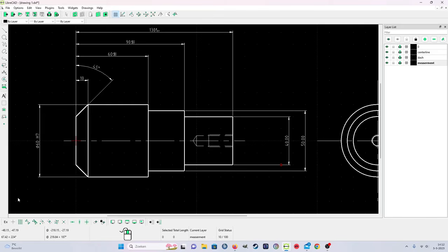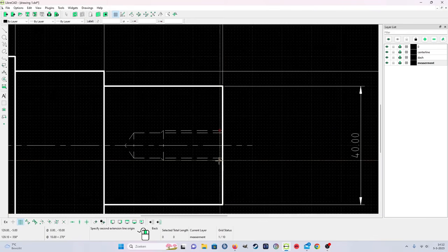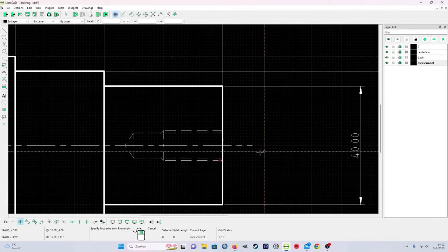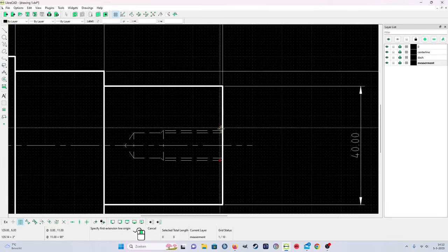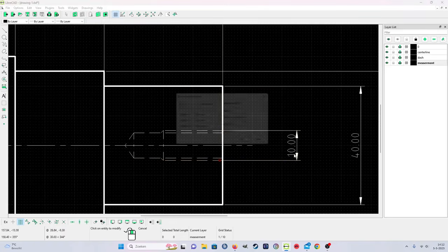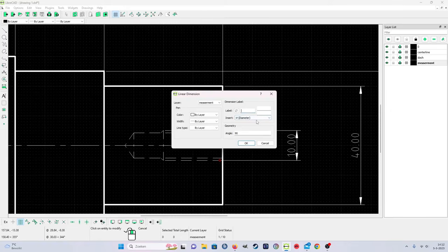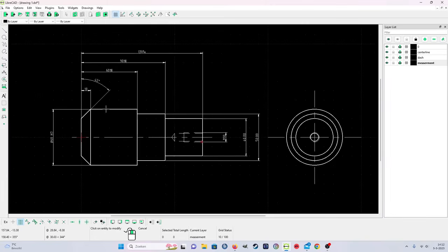Okay, now with the thread hole. Vertical. Let's put the grid on and let's make it a little bit easier for me. From here, I know that's 10 mil. Oh, I put the wrong one. If it's wrong, just press your right mouse button and you can start over. Yeah. From here to here. Also properties, and that's of course M10. Like that. We got nearly everything. Yeah? From here to here. There.